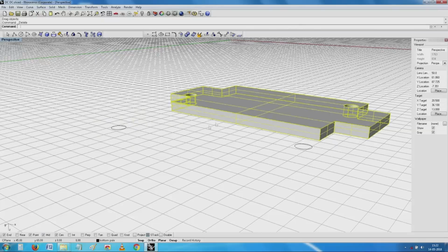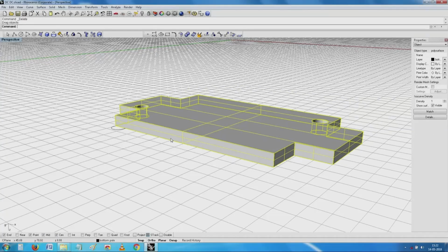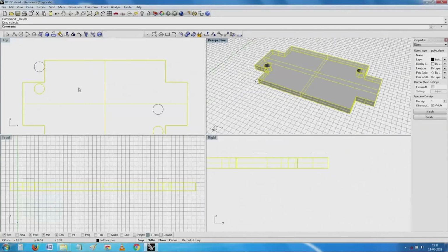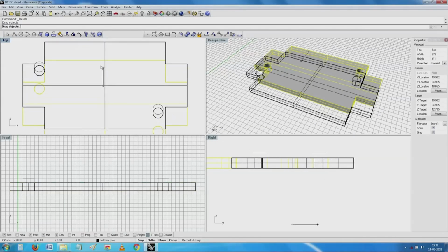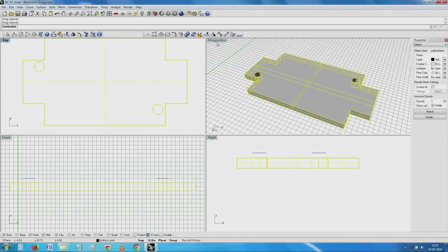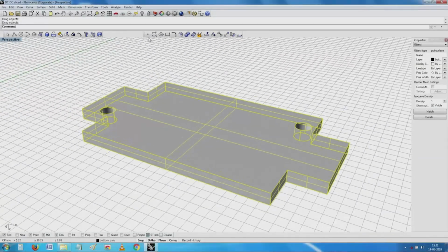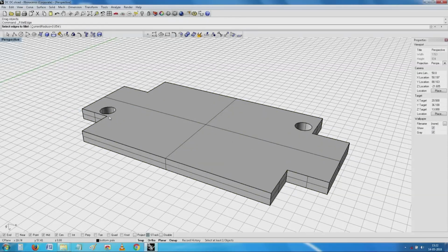All right. Now, this being a sheet metal part, it invariably requires the filleting part. So, I will fillet this edge, in fact, I will give a very generous fillet.